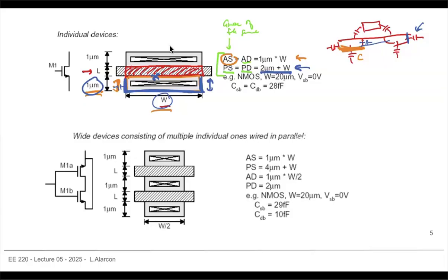And if you put in 0, that's not a very good simulation, because you run a simulation, you run frequency response, and you get very good numbers just because you did not consider any of the junction capacitances.